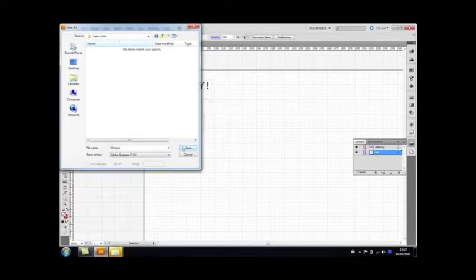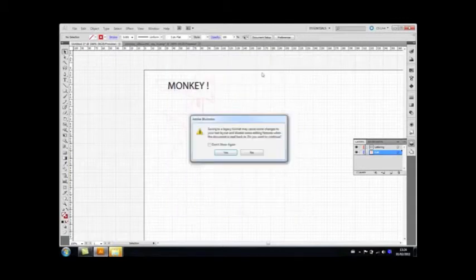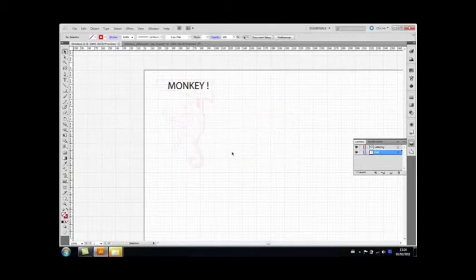And save. So just save as an Illustrator. Right, this is important as well, guys. Up here we'll have the version. I'm using CS5. On the Lasercutter though, however, it's using CS4. So in order to be able to open up our file, we need to make sure that it's backdated. So select CS4. If you're using CS4, then it's fine. You can just go ahead and save. So select CS4, click OK. Yes. And that will save it. Now we're ready to take our file across.